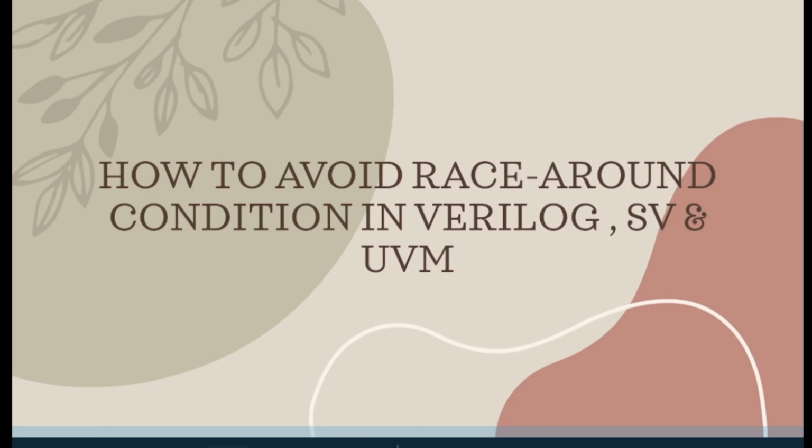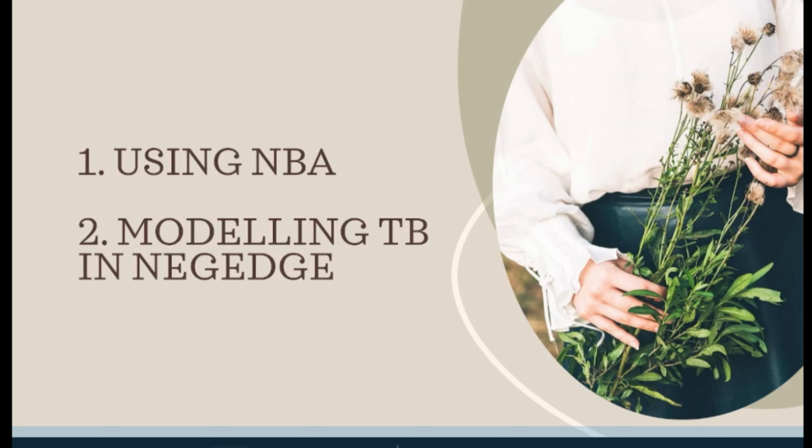Coming to today's video, there are many ways to avoid this race around condition in Verilog, SystemVerilog and UVM. Let us see them one by one. Coming to the first thing, which is Verilog. In Verilog, there are very limited options to avoid this race around condition. The first is using non-blocking assignments. By using non-blocking assignments, you can avoid the race around condition compared to blocking assignments.